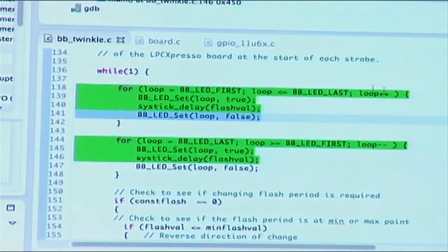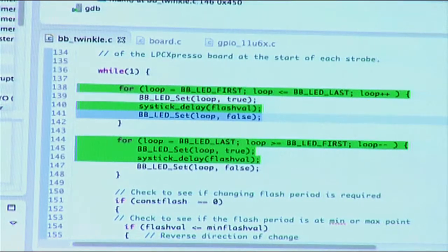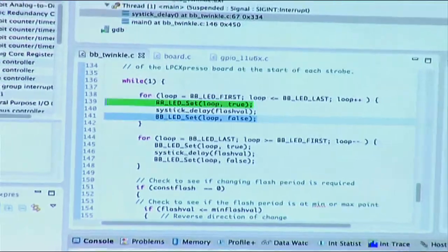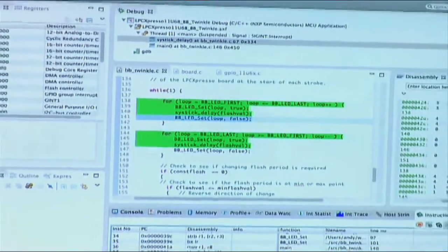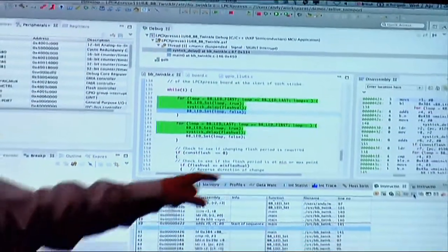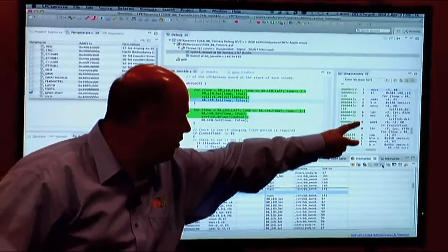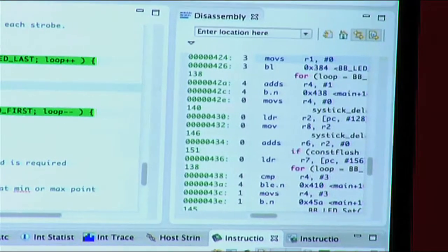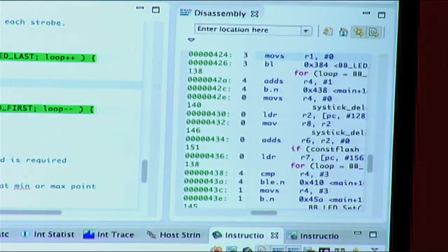That profiling information can just be turned on and off using an option inside the trace view. The other thing that we get regarding profiling is the numbers that we've got on the screen here. That tells us how many times each of those instructions exist inside the trace buffer.